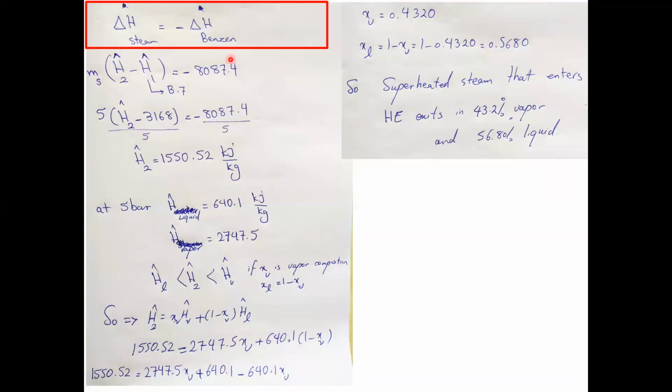So now, as I mentioned, this amount of the energy that Benson gains, steam loses, right? So you can say this one you already quantified. That is the values you get from the table, right? So you know, in the beginning, you don't know what phase you have, so you have no idea what the enthalpy is. At the initial stage, it is superheated steam at a specific temperature and pressure.